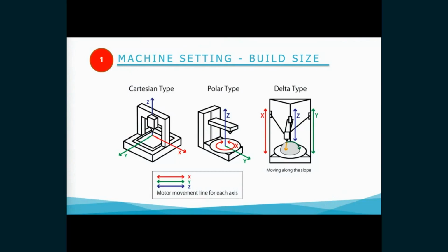Profiles in 3D printing are the set of parameters that define the machine settings to print a part through the use of slicing software. When varying any of the slicing settings, the results obtained may consequently be different. Since every material and every printer are different, 3D printing settings will need to be adjusted to reach a good print quality. Also, depending on the geometry of the 3D file, sometimes we'll have to fine tune it.